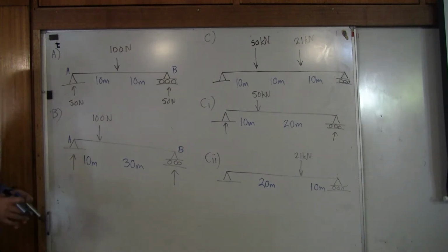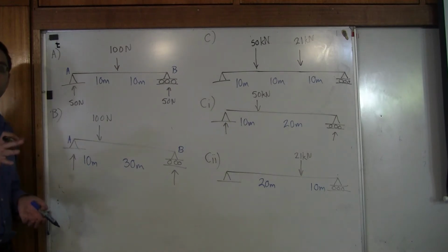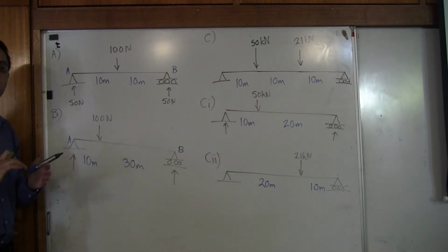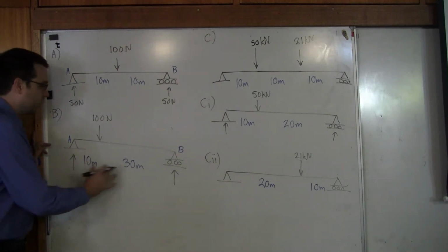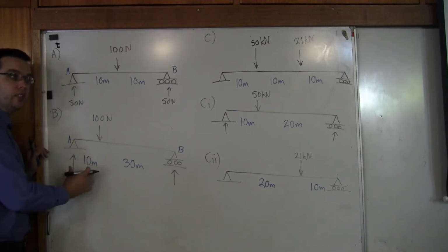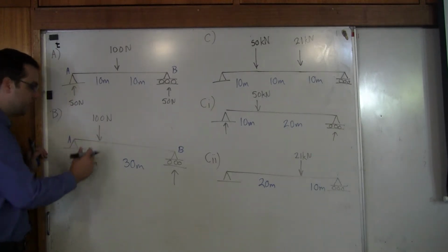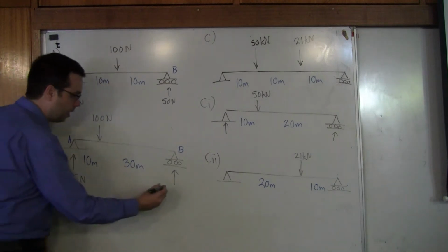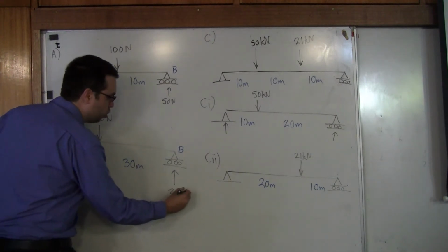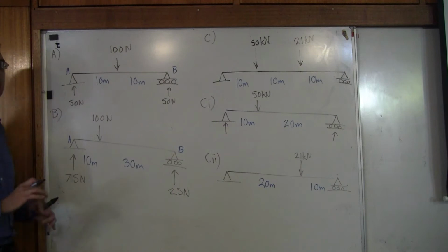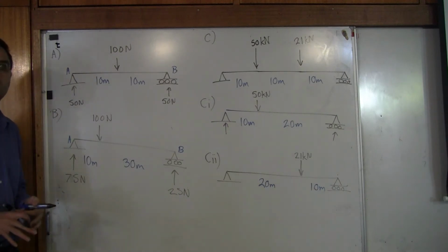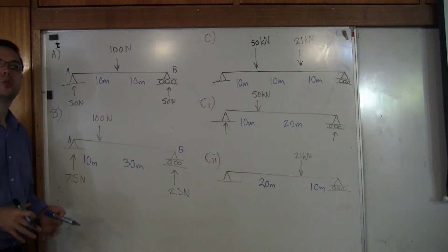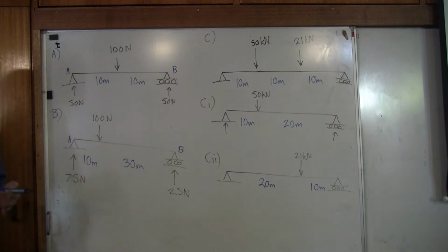Now, how much more weight do you think he's going to be holding? I heard a third, or like 3/4. 3/4. There we go. That's better. 3/4. So because there's 40, he's 1/4 of the distance, he's going to be taking 3/4 of the load. Now I'll say that this is not the way we normally teach this topic. I just want you to know that this happens to be true. And it's intuitive. I'm trying to use what makes sense to you in your head.